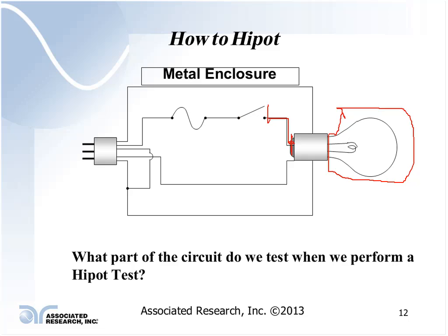Again, I'm applying high voltage to the hot conductor. It goes in, goes through the fuse to the switch. I'm applying it to the return. It is on my neutral side, or not to the neutral, not to the return, I'm sorry. And that is testing the neutral side, applying high voltage to that. My return lead is connected to the enclosure of the product.